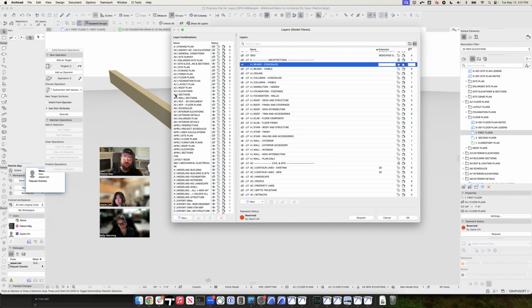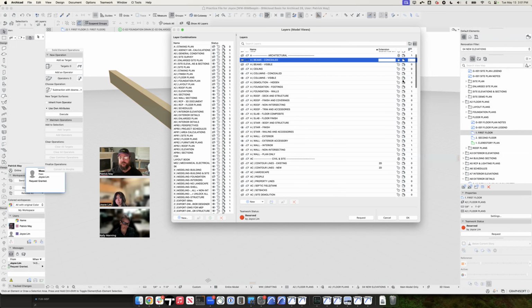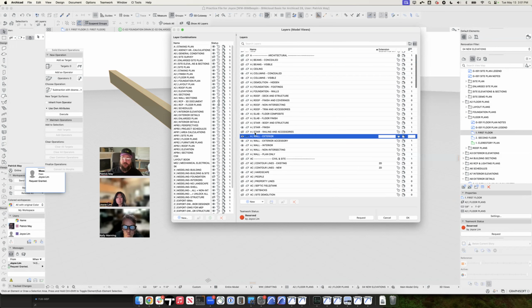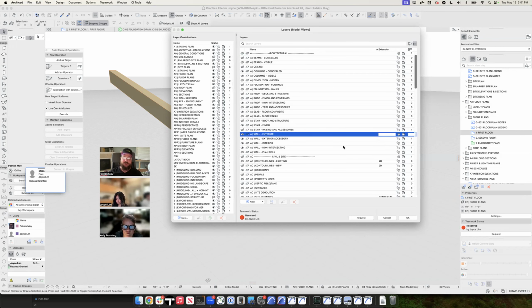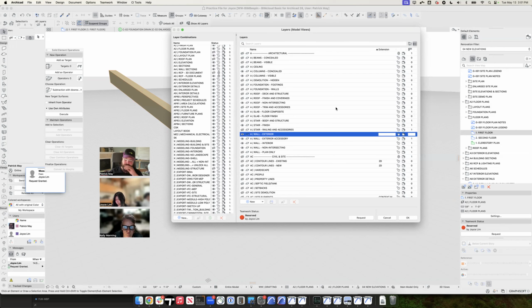If I were to put both of these beams on the ceiling layer and make the ceiling layer visible, they're not going to intersect with each other because zero does not intersect with zero or anything else. One is just the standard default. This element is visible. The exterior wall layer, for example, is visible for pretty much everything, and it's set to group one for everything.